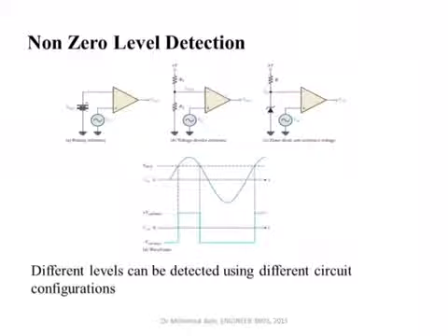In the previous circuit, I compared to a voltage of 0, but this does not have to be the case. For example, here I'm comparing the positive terminal to a battery of value V reference. So when Vn exceeds Vref, the output will saturate at plus VCC. When Vn drops below Vref, the output will saturate at minus VCC, as shown here. So this is plus VCC and minus VCC, the maximum and minimum allowed output voltage.